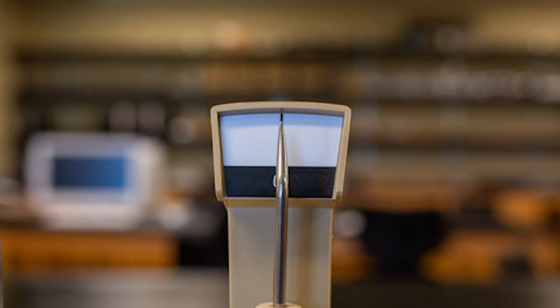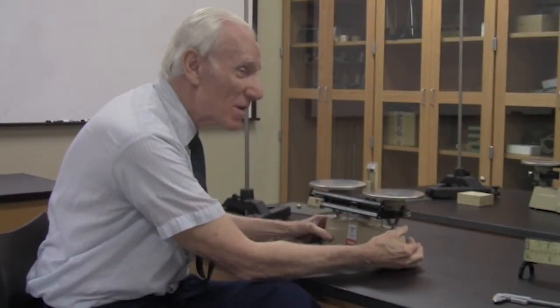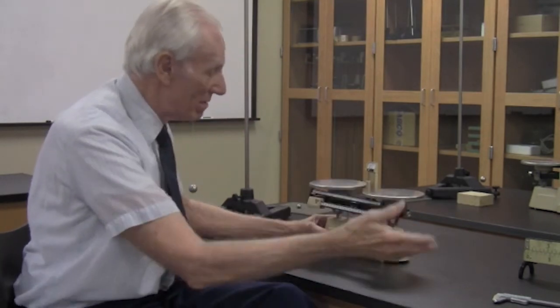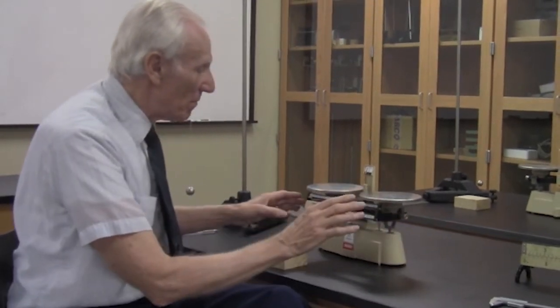If it isn't set at exactly 0, there's a knob here which you turn like a tenth of a turn, one way or the other. You'll have to figure out which way to turn it to make it balance the right way. So I would turn this by a little bit, a tenth of a turn, if it's really close to balance like this is, and then see if it's closer to that 0 mark or not, and then keep doing that until it's on the 0 mark. This is, of course, a systematic error, which we want to eliminate. And we can eliminate it by making 0 really 0.